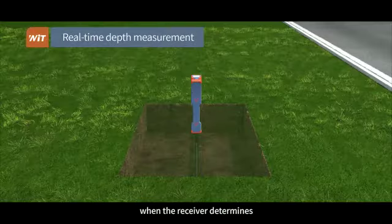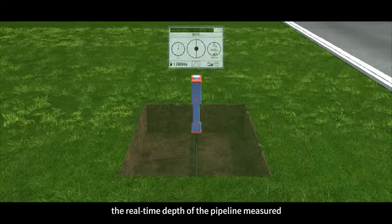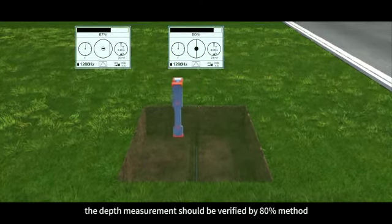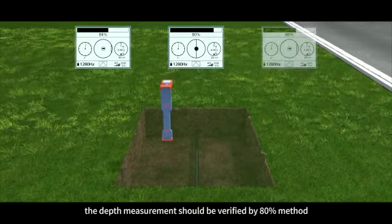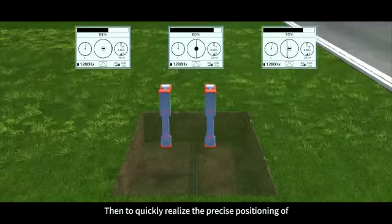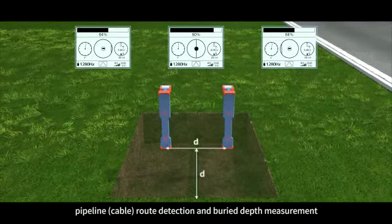When the receiver determines that it is basically above the pipeline, the real-time depth of the pipeline measured will be displayed on the right side of the screen. When the pipeline is deep, the depth measurement should be verified by the 80% method. Then you can quickly realize the precise positioning of pipeline cable route detection and buried depth measurement.